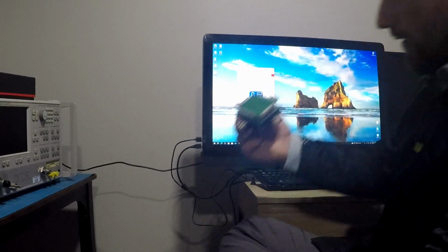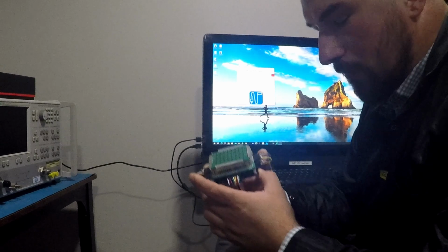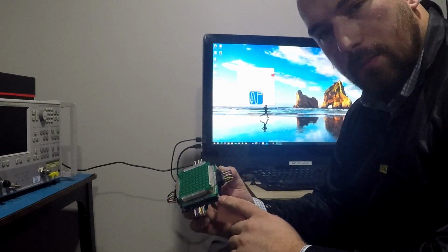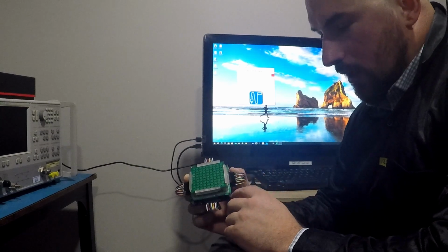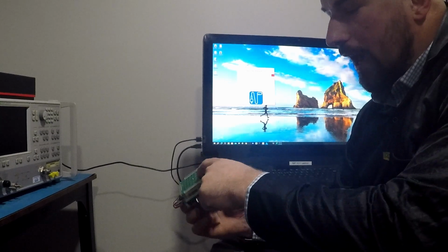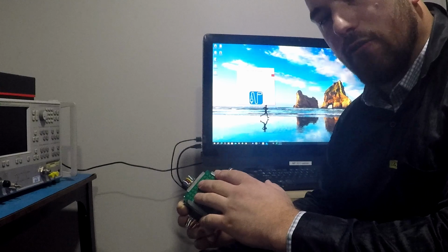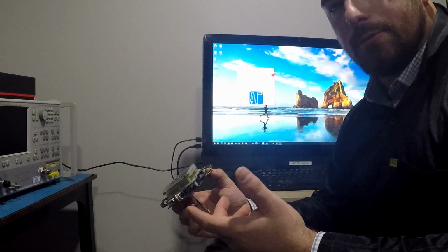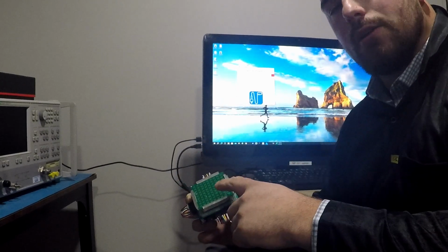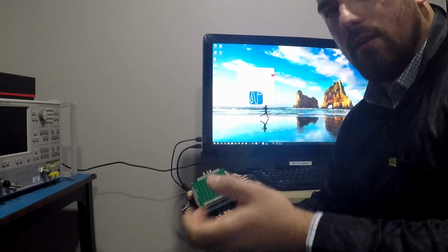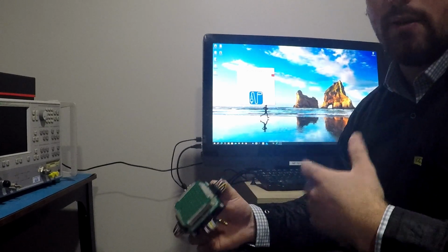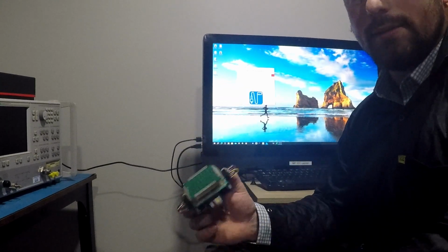So here's the antenna that we'll look at. We have the main logic board below, and some of the DC breakout board here. It's connected to the actual antenna, which contains all the RF portion, through about 500 pogo pins. There are about 144 individual RF switches, so we needed a lot of pogo pins to make it work.